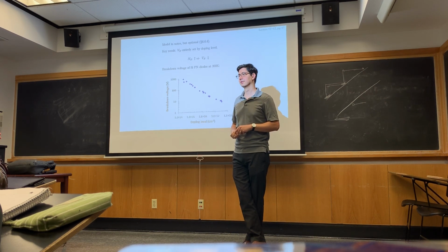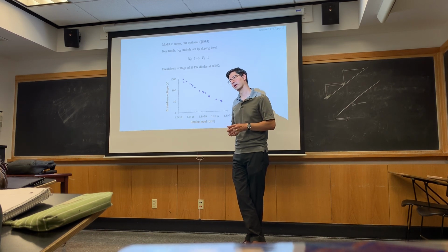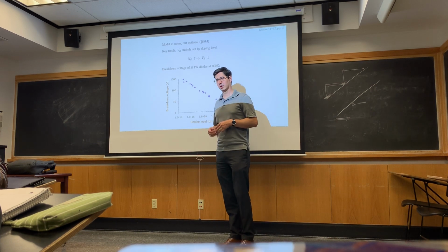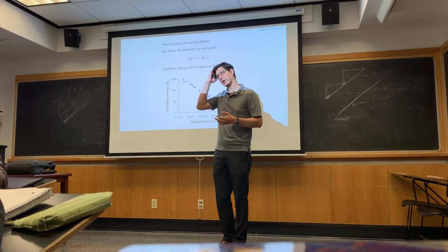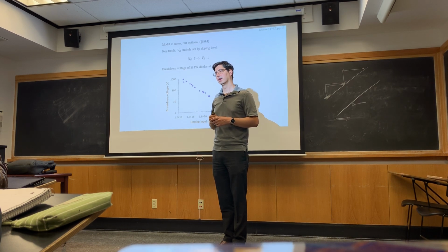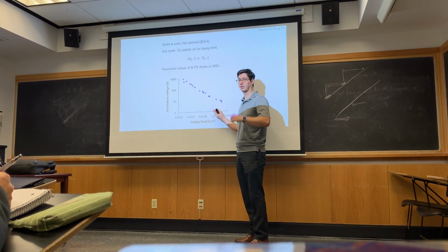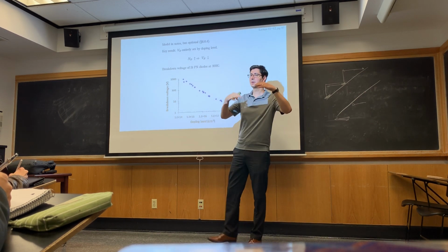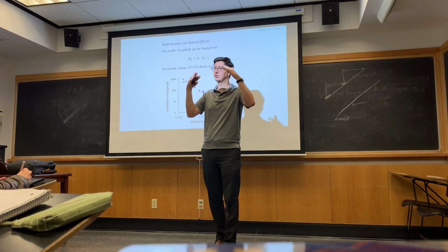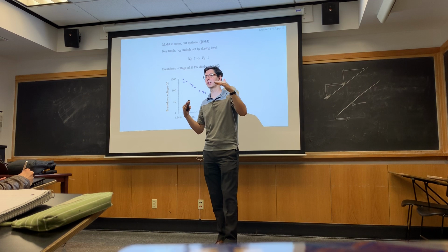It should be... I would think of it as a minority carrier in the depletion region, right? So weirdly, the higher the concentration of doping on both sides, the lower the concentration of the minority carriers. But yeah, you have a higher field, right? So even at zero bias, the higher your doping is, the higher the electric field. Phi BI is staying about the same for these devices. Yeah, it might change by a little bit, but it's around 0.7 for silicon.